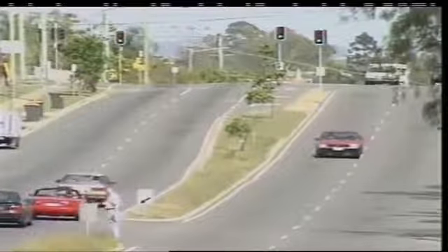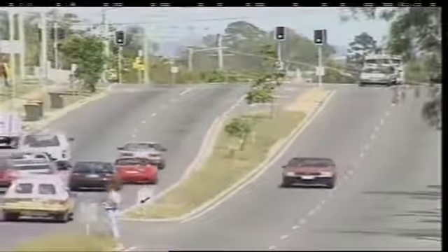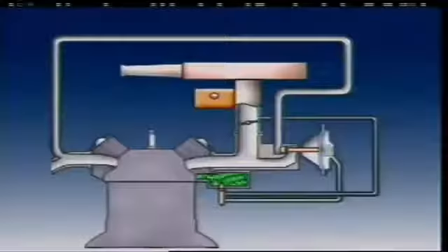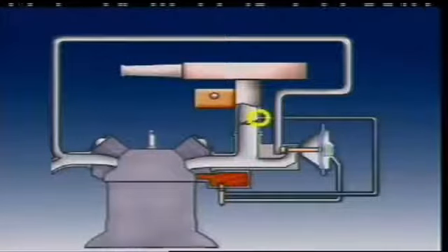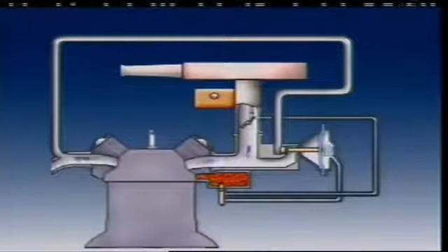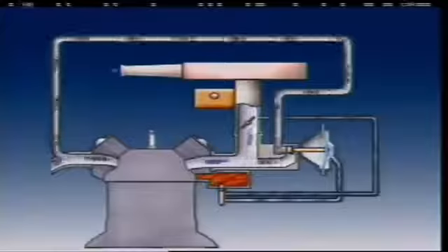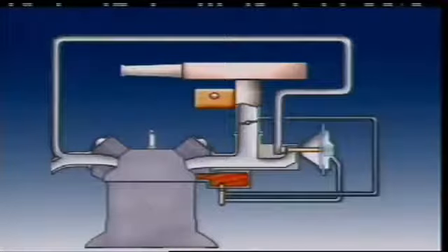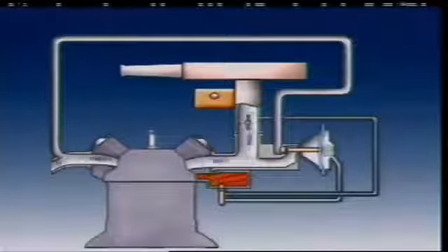The EGR valve usually opens when the engine is at normal operating temperature and likely to be using a lean mixture. When the engine first starts, and until it warms up, a temperature-sensitive valve prevents manifold pressure reaching the EGR valve and stops it from operating. Manifold pressure reaches the valve when the engine is warm, and when the EGR port of the carburetor is influenced by the position of the throttle. This is generally at light throttle openings, when a lean mixture could cause increased oxides of nitrogen. It does not operate at idle or at wide open throttle.